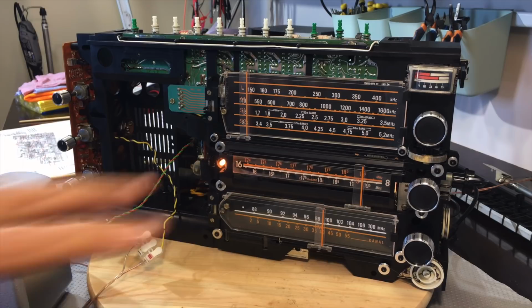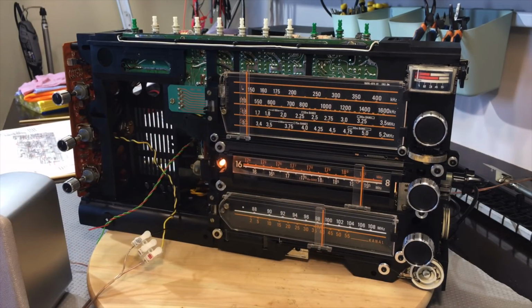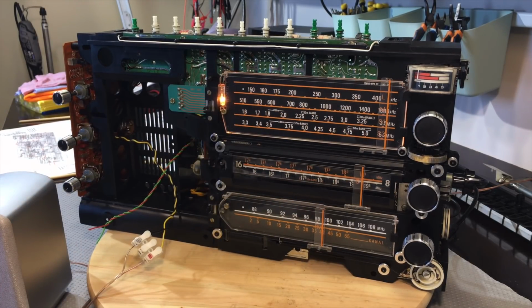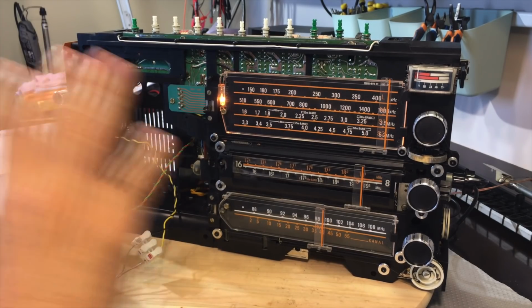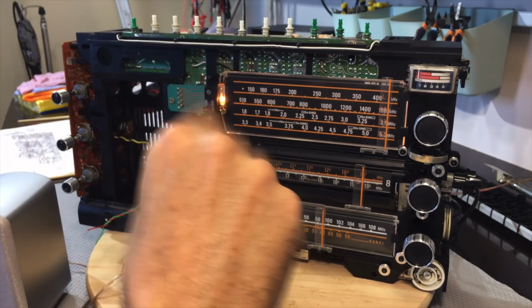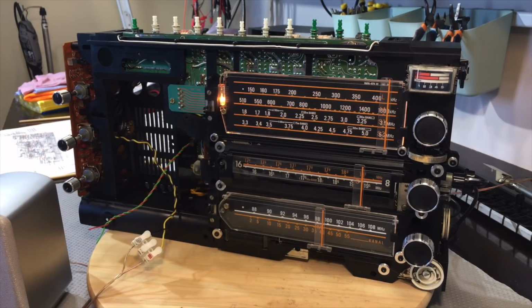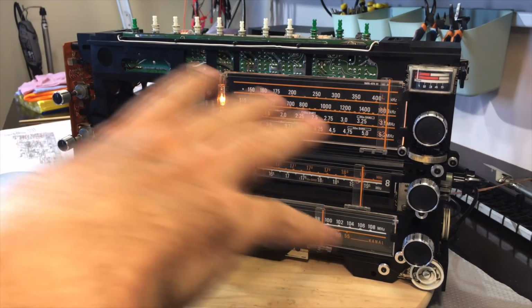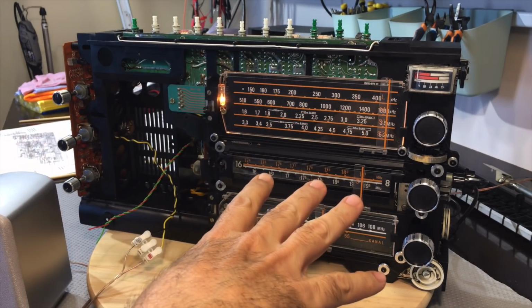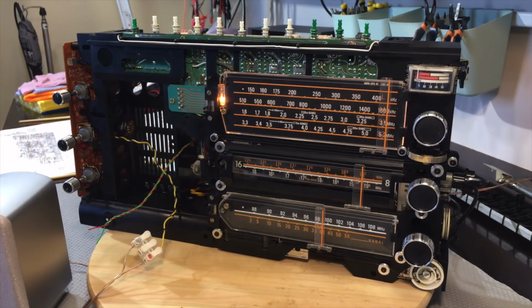And I think the most obvious was actually on the medium wave. This is amazing. Enough said. I am extremely happy with that result. I know I keep saying this, but I really am. And I now have satisfactorily completed, to my satisfaction anyway, the IF alignment for the entire spread of the AM. I have not touched the FM, obviously.